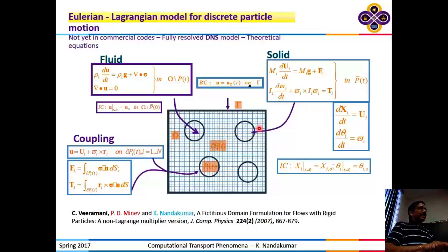That concept is already there in COMSOL, but for fixed spheres. In fact, when you do the physics-based grid generation, you have already noticed and asked the question, why does it put more layers near a solid boundary, and why does it have a structured mesh there, right? Because it knows from the physics of fluid mechanics that you will typically have a boundary layer. So you need a lot more grid points to control the numerical error, right? So that's a concept that has been around for a while, to do dynamic mesh refinement to improve the accuracy.